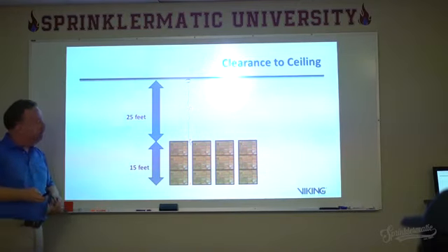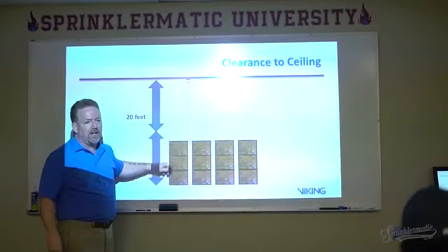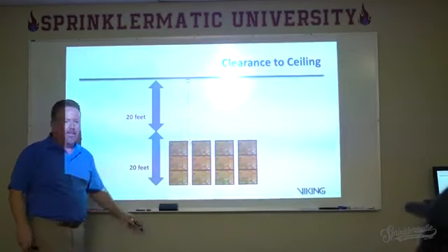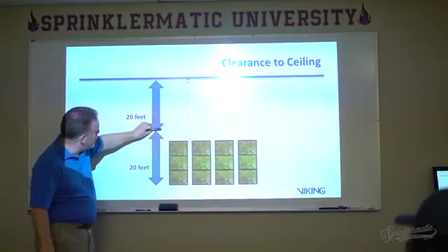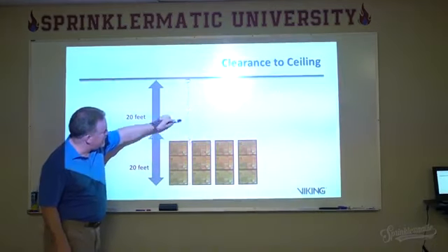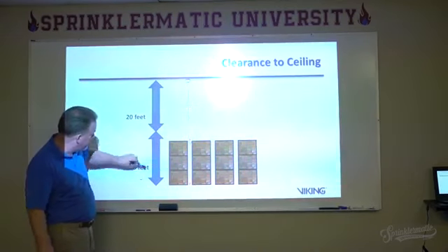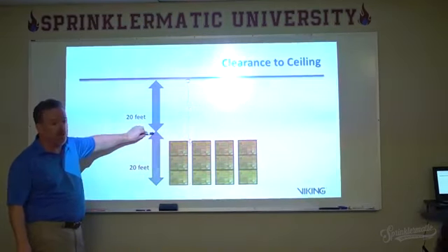Not necessarily. So what we have in NFPA 13 is a limit to the open space above storage. Even though the owner is saying, I've only got 20 feet of storage, the designer is going to be required to design as though there is phantom storage up here up to 20 feet. So right here I would have to go to what? 25, right?